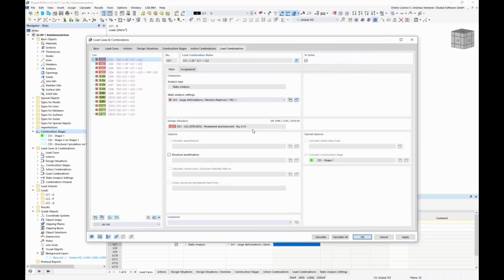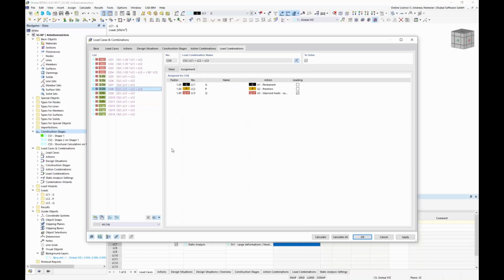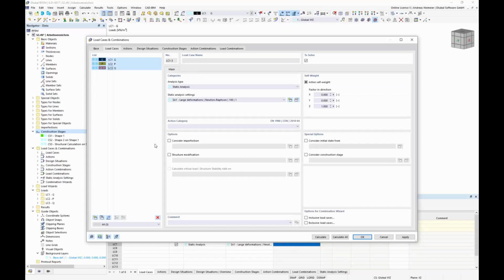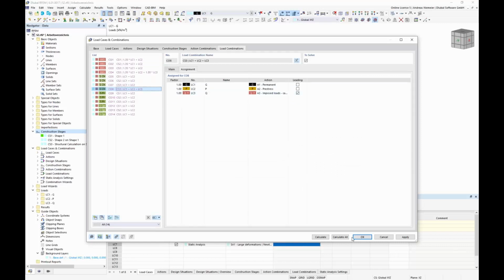And if we go back to load combinations, you see the list is a little bit longer, but now has a stage allocation: stage 1, stage 2, stage 3. Here we have 2 combinations, the same for the characteristic ones. And as you see, we have now even defined stage 2 as the basis, working on the element set of stage 3. So even this setting is pre-filled with all load cases. Now we can start calculating all. Before, I would say let's deactivate some load cases so we don't have to wait for all, and calculate simplified a little bit. No, we can calculate all.